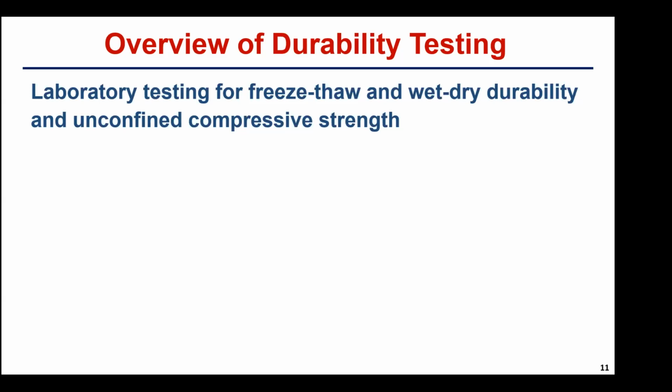And we also wanted to do some unconfined compressive strength testing. And the idea with the unconfined compressive strength testing is that the samples that were constructed in the field were constructed 4 years ago, almost before this study was done. And then for the new samples prepared in the lab, we had to bring new cement and new fly ash because of the shelf life of these materials.